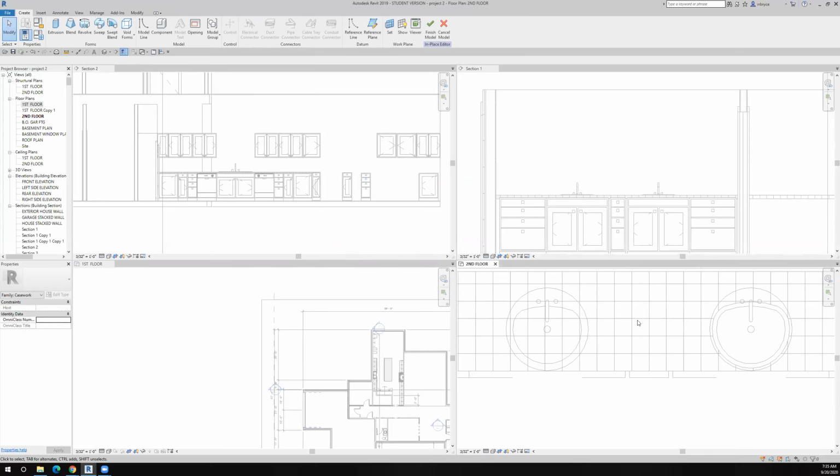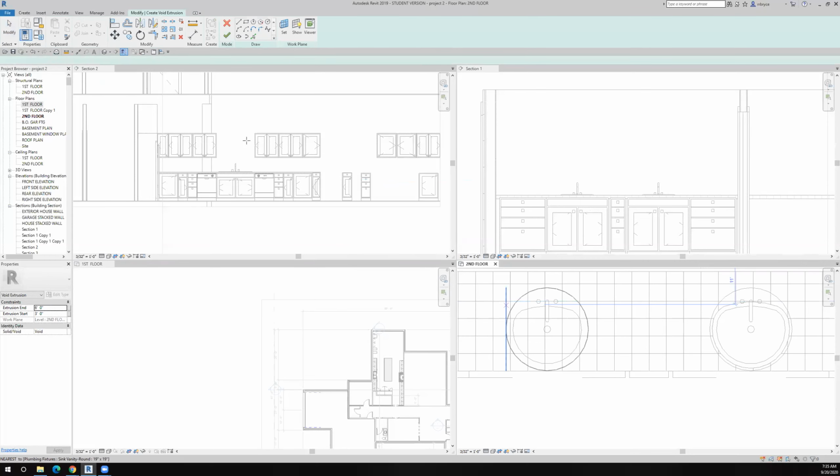This should work now. And this was my active view, so Revit was saying, well, what plane do you want me to cut? So I would have had to define a plane here, but I'll make this my active view, and it should work now. Yeah, and so I'm going to pick a line, do the offset again, which is what, 1 inch.